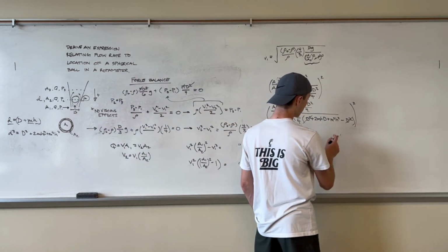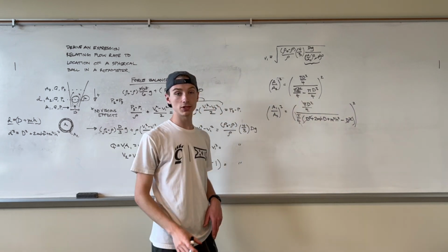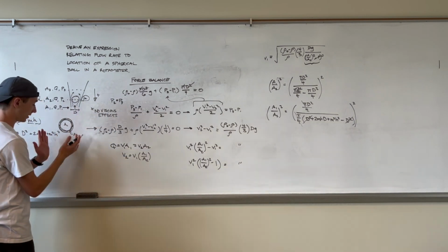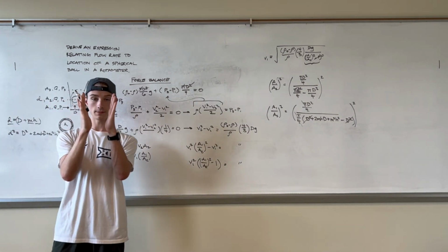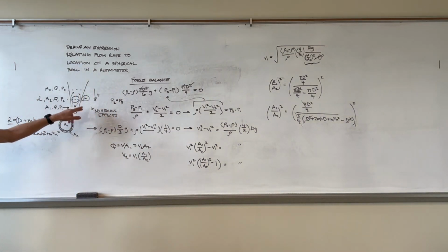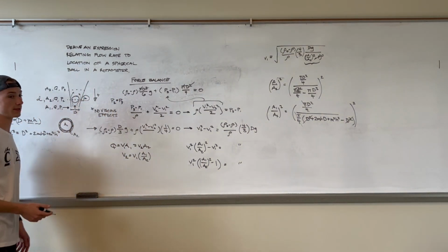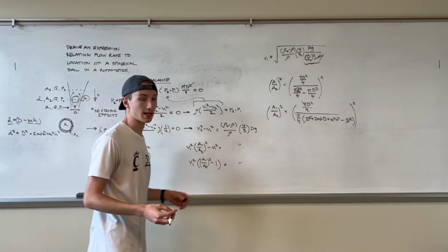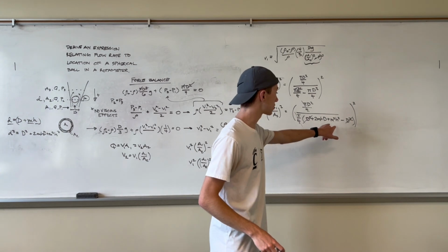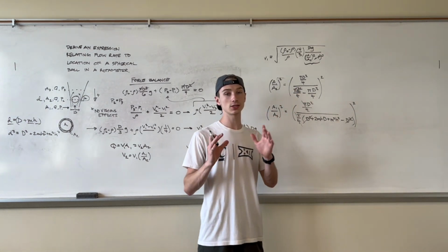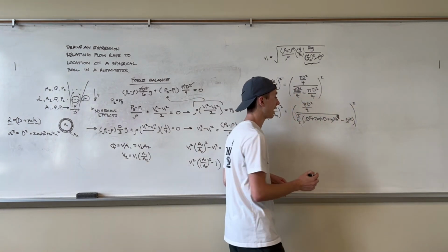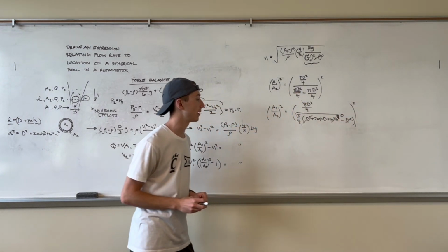Now again, we have another approximation that we can make. m is the slope of this tube. It's very small. I mean, these tubes in real life are hardly conically shaped, but they're really slightly sloped. And then the height of the ball is also going to be very small. It's on the order of centimeters, or 10 to the negative 2 meters, right? And so when we multiply the squares of these numbers together, it's an extremely small number, which we can basically just negate as 0. Okay, we don't even have to worry about this.